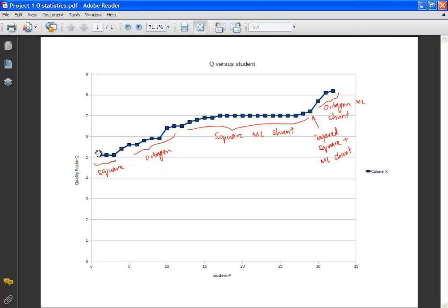When you come to the VCO project, your inductor is pretty much going to be the most critical portion of your design. Okay, and for that you will not be allowed to use a simple RLC model. For the VCO project, you won't be given the value of the inductance like in the other projects. You will have to choose the value of inductance which is best for your noise and your other parameters. Then you're going to go into ASITIC and model the inductor for that particular value, and you will see, as we'll see in class, that your phase noise has a very strong relationship to the Q of your inductor, which again dominates the Q of the tank.